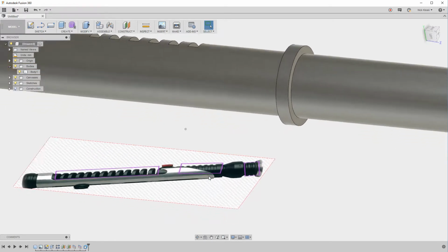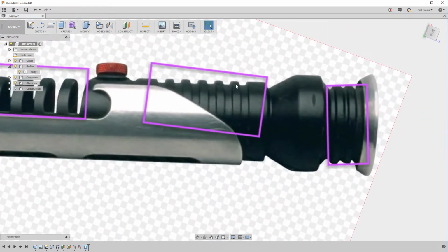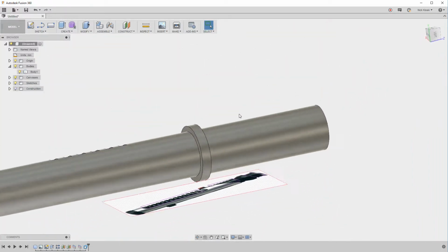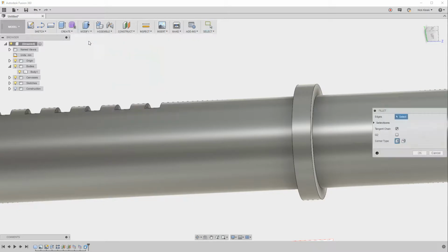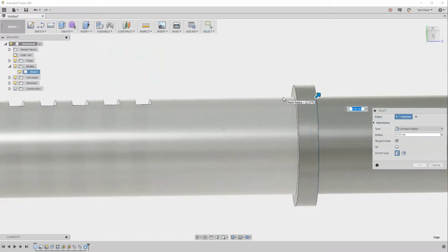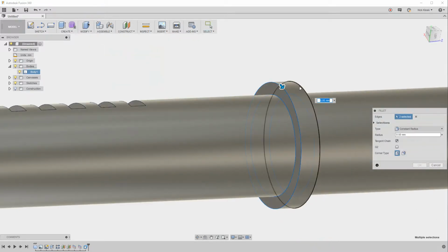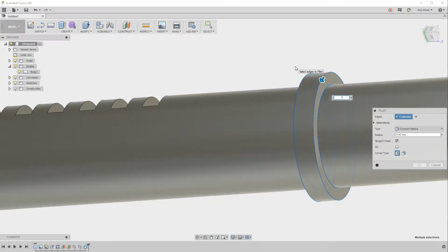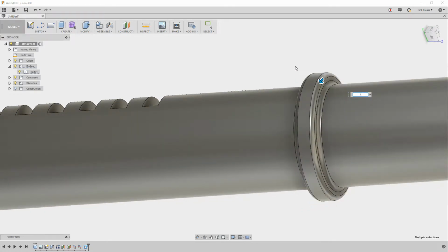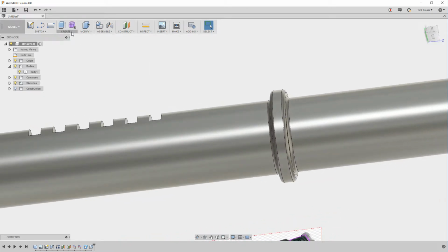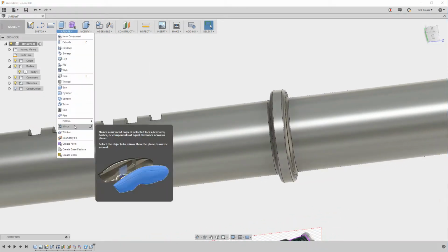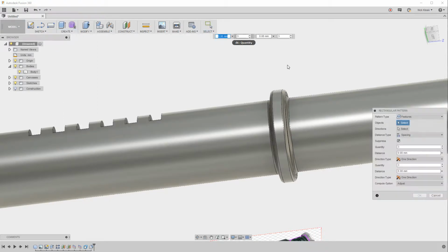Now those are kind of nice. If you look at this, there is kind of a little U-shaped sort of guy right there. And that makes for a little bit easier transition. So I'm going to go to fillet and click on all four of these and try to put in a fillet. 1 millimeter. Looks pretty good. And again, we're going to go to create a pattern, rectangular pattern.